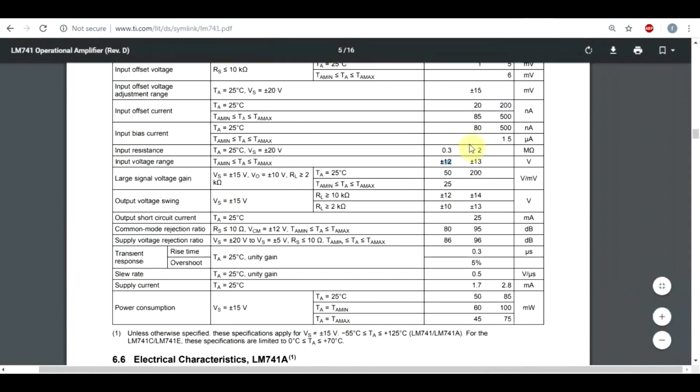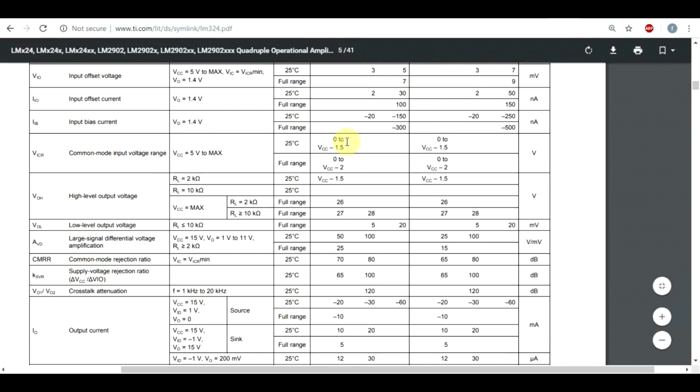Whereas before it was defined as a voltage difference from both supply rails, so 2 volts from the positive, 2 volts from the negative, for this op-amp we can see that from the ground there's 0 offset, so you can go directly to the negative voltage, whatever it is, but you have a limitation from your positive voltage. So we can see that it's the positive voltage minus 1.5 volts on the input. And if we consider the full temperature range, then it will be 2 volts. So again, this is a problem of the input stage, and we'll be looking at that in a moment.